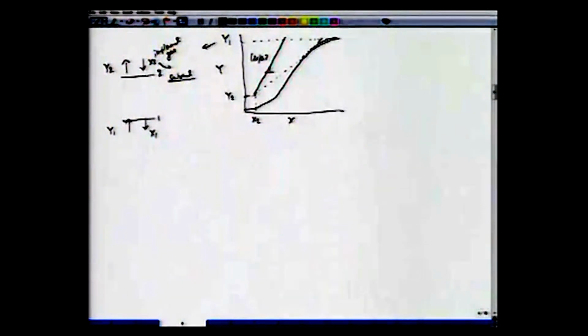In other words, we can see that there is a pinch here where the driving force for mass transfer, del y or a small del y, has become 0 here. So the driving force is 0 here, and we require an infinitely long column here.